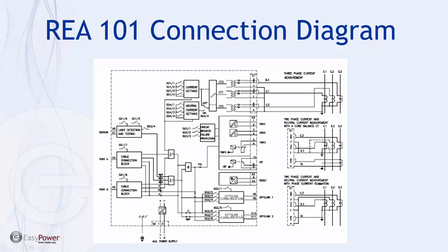devices work. Over to the right, you can connect your CTs. You can use either a zero sequence CT or a residual for the ground input. You use the other 2 CTs for phase inputs, or you can just use 3-phase inputs. And there you can use the 1 or 5 amp nominal rating.